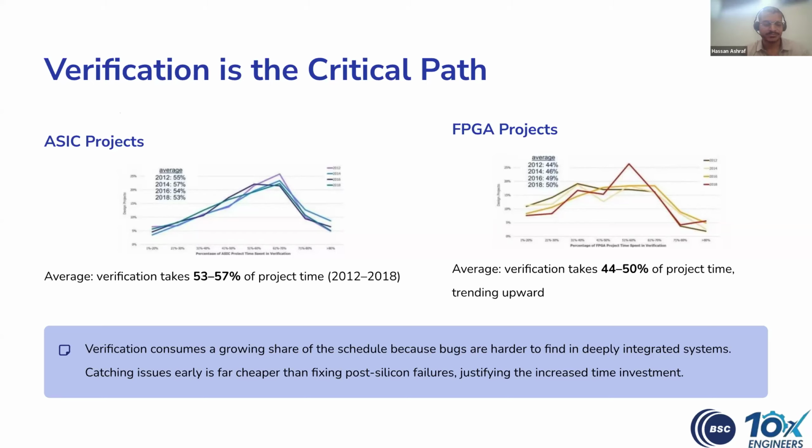are required from the very start of the project, because if we skip any bug in the pre-silicon stage and we find that bug in the later stage, post-silicon on our actual board, while doing the testing with the oscilloscope, it would cost so many dollars and so much time, because you have to repeat the complete cycle again. You have to update the design accordingly. You have to do the PD again, and then you have to do the verification. You have to run all the test cases again to make sure that the bug is fixed and it's gone. So verification is required from the very start.